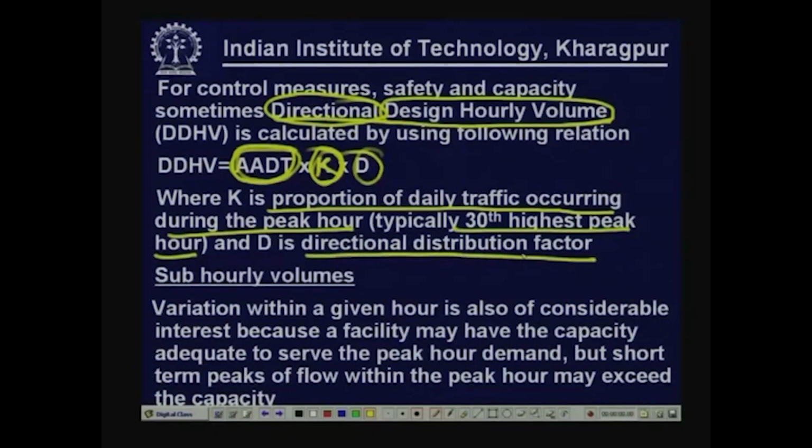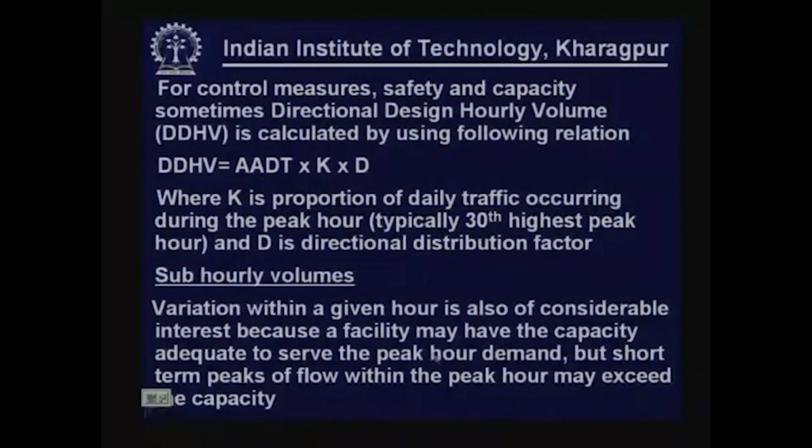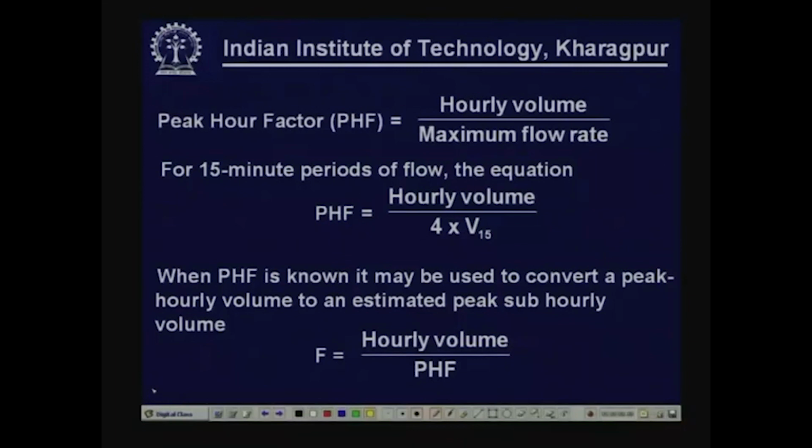Sometimes we even see the sub-hourly volumes, because variation within a given hour may be important. You may find the facility has a capacity which is adequate to serve the peak hour demand, but short term peaks of flow within the peak hour may exceed the capacity. So, therefore, we may need to look at the sub-hourly volume also. There, in that context, we use the peak hour factor.